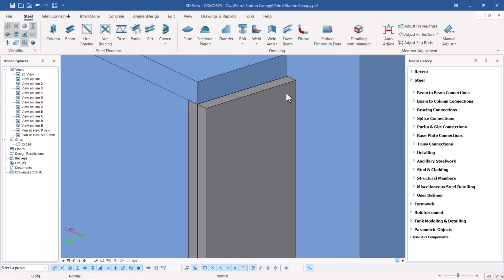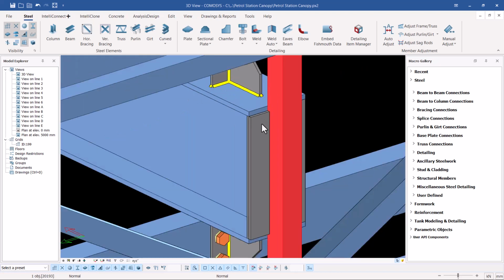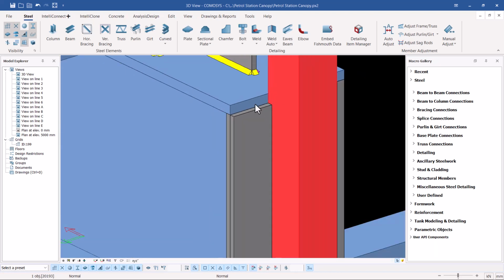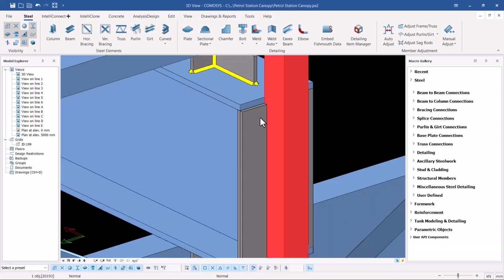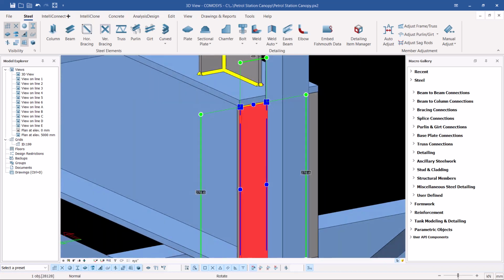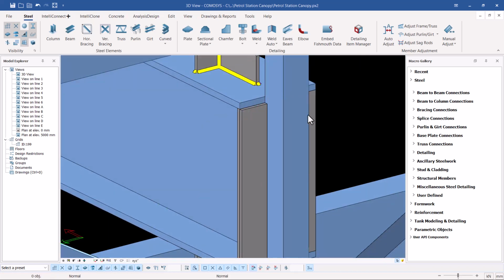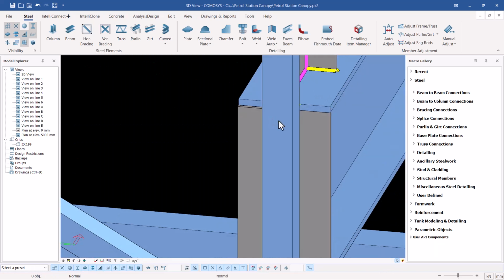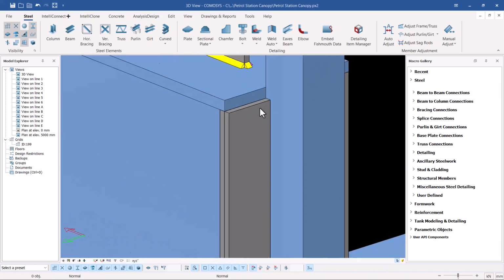This plate will be welded to that member of the girder, and we have to mirror this on the other end. To mirror also depends on whether this strut is actually right at the middle of the web. If you're not sure of that, we'll just copy this plate to the other end.